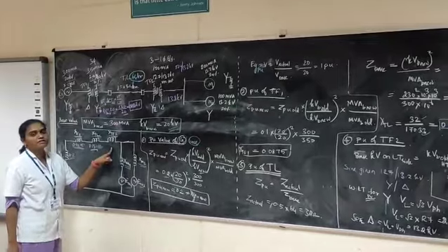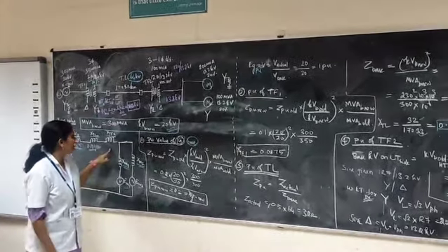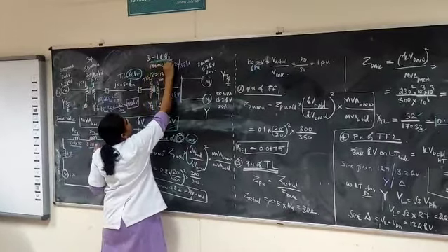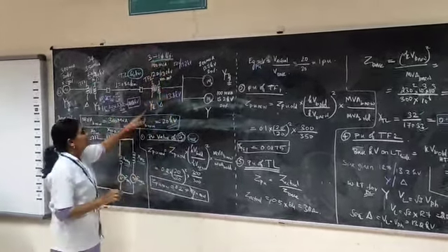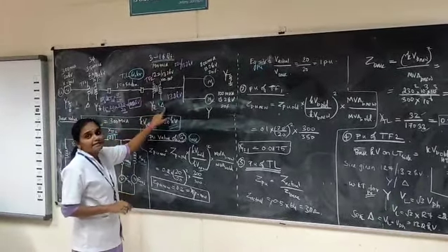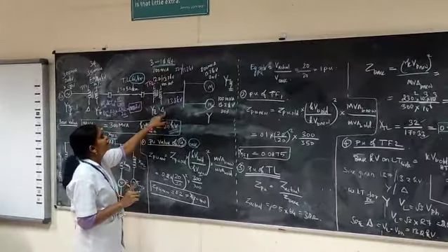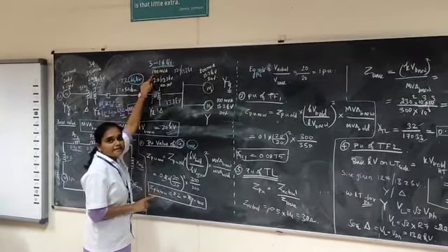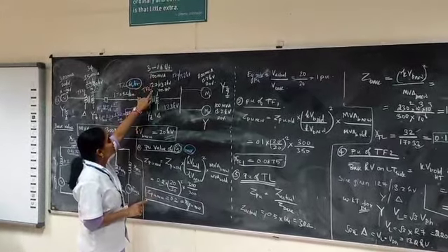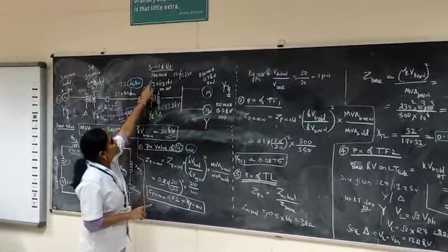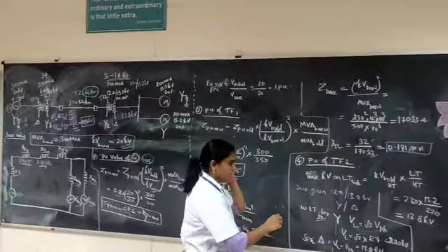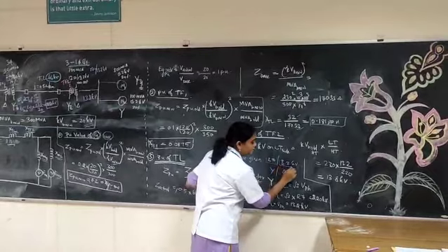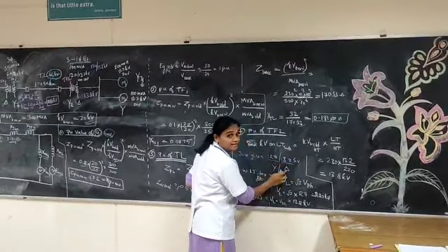Next we have to move to transformer 2. If you see here in the question, it is given as 3 single phase transformers and the connection is star and delta. So first, we have to convert these 3 single phase transformers to 3 phase transformer ratings. For that we have to change the voltage levels. The given rating is 127 by 13.2 kV, star and delta.